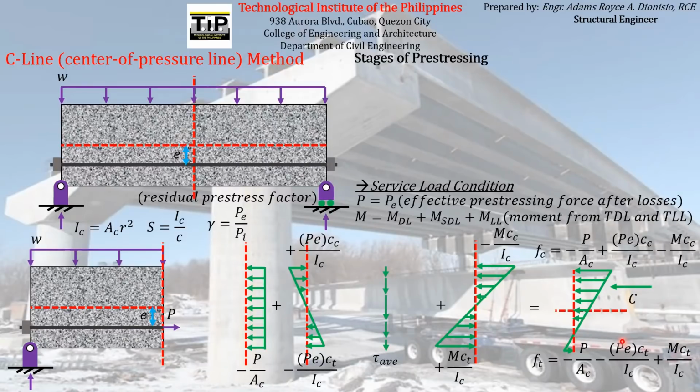And if we try to find the resultant of those two single forces, which are the resultant of this larger triangle and this smaller triangle, we can see that their resultant is a single force that points leftward. Why? Because obviously the direction of the resultant of the larger triangle will govern, which is leftward. So we can just call that single force acting leftward C, the total compressive force experienced by the concrete element.